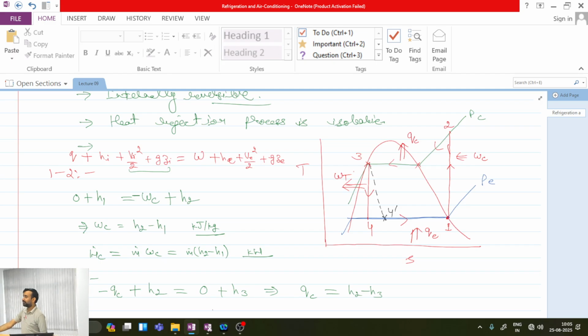Another important issue is that the cost of the turbine is very high. That can increase the overall cost of the system significantly without any added advantage of the turbine, which could be in terms of work if we expand a high specific volume substance over it. So now we will go towards a more practical vapor compression system, in which, from process 3 to 4, the turbine is replaced by an expansion device.